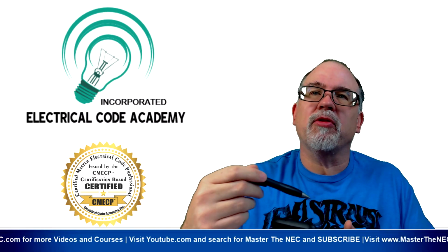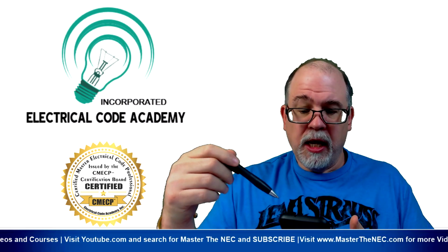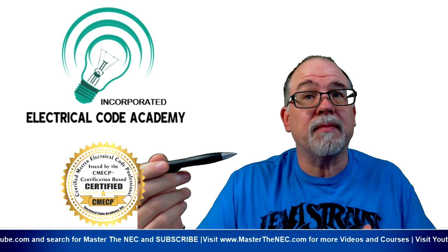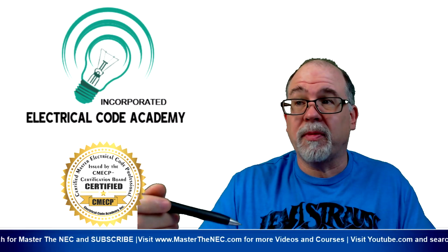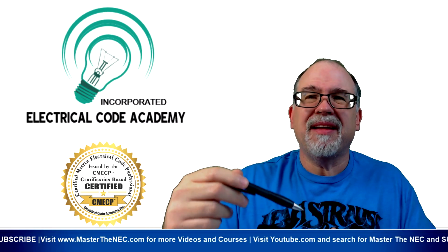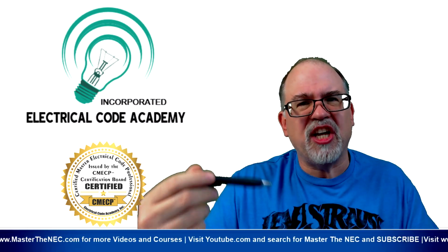If we size those conductors at the 90 amps, which is the primary current, then I couldn't terminate that on a 225 amp rated overcurrent device, because that wouldn't be protecting it at its ampacity. That would be a problem. So typically what we do is assume a continuous load if we don't know otherwise. And I'm just giving you technical practices. I told you what you might get on an exam, but in the realistic world, we would do this at 125%, and that'd be our suggested value.